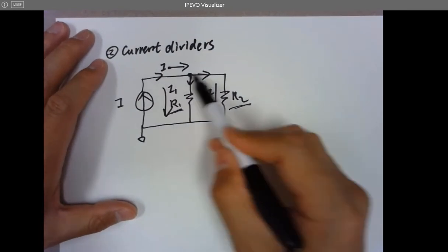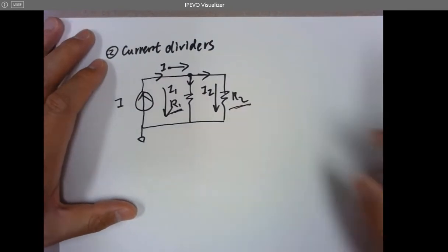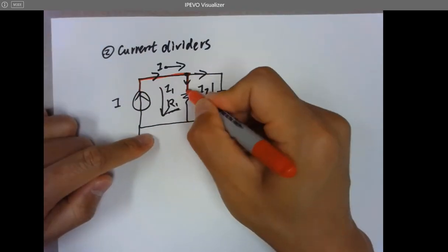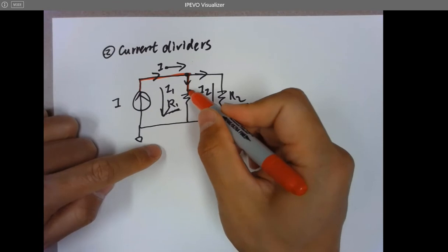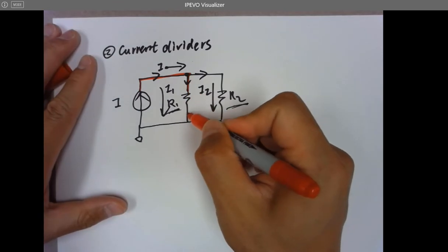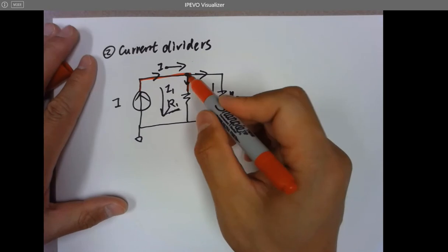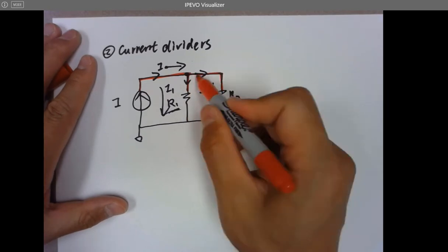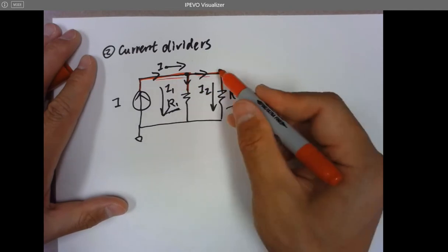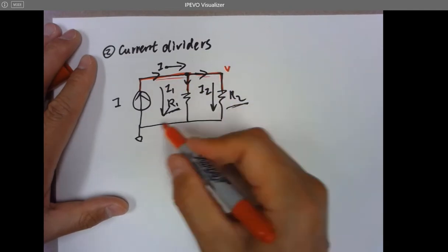This is one voltage node, right? Make sure you understand this concept. They are one piece of metal until the resistor, because every time it goes across a resistor, there will be a voltage drop. However, before that, it's fine. They're all metal pieces, so they share the same voltage potential, which is V, and this is ground.